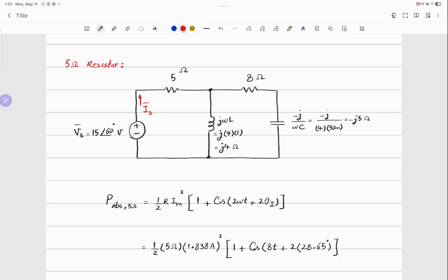Do you like to do nodal analysis when complex numbers are involved? But you could do a simple calculation. Unless you can somehow smuggle your math cat into the exam. I mean, there's a way to do it that simplifies the math. What is the simplest way to find either the current or voltage of the inductor? Current division or voltage division. Current division. Why? Do you have IS or no? Yeah. Can you just divide it between the two paths? So you go for current division.